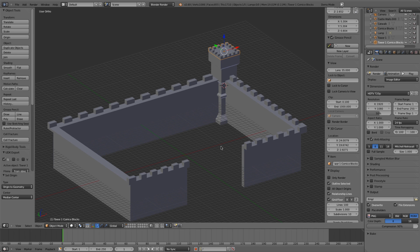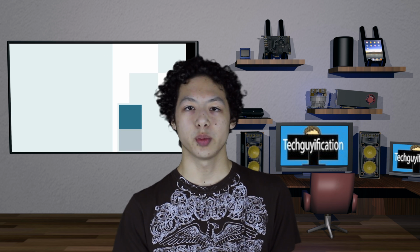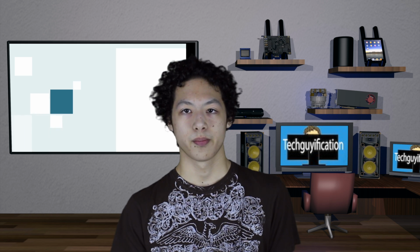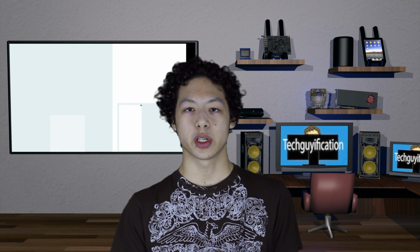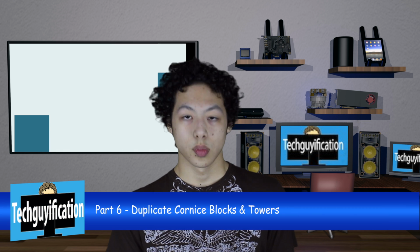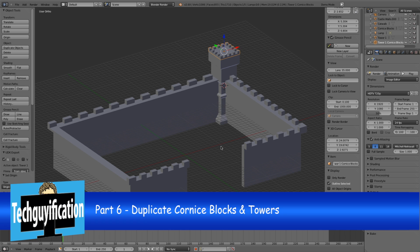Press Z to go into solid display mode and pan around so you can see what we've done so far. At this point, you can save your Blender file, again with Ctrl S on Windows, Command S on a Mac. The next thing we're going to do is duplicate the towers and the cornice blocks on the towers. So next, select Tower 1. Make sure not to select Tower 1 Cornice Blocks, but the actual tower.